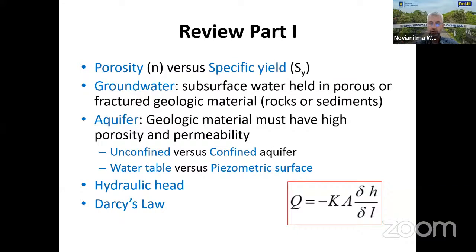The hydraulic head, if you remember, is basically an energy level that describes how much energy a given amount of water has at any elevation. We used that concept, the Bernoulli equation, to describe how flow of water is being initiated and based on physical terms. And then at the end of the lecture, we talked about Darcy's Law.